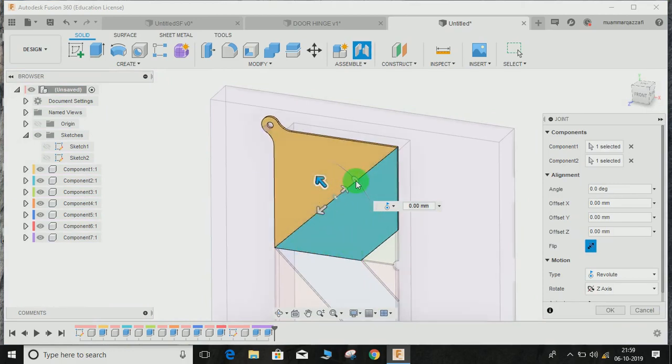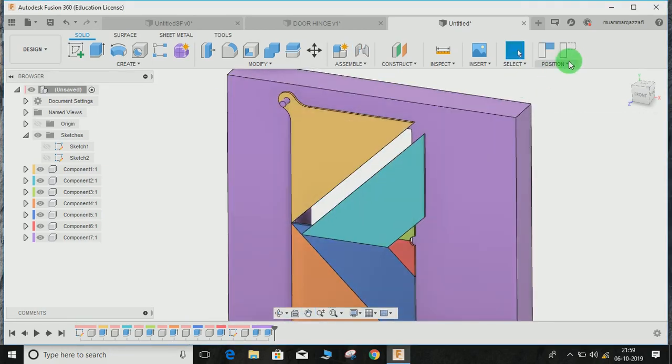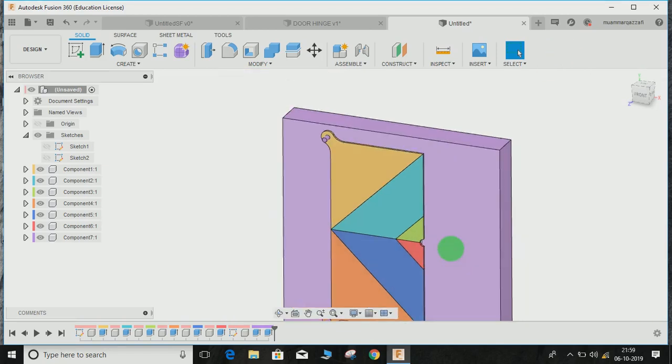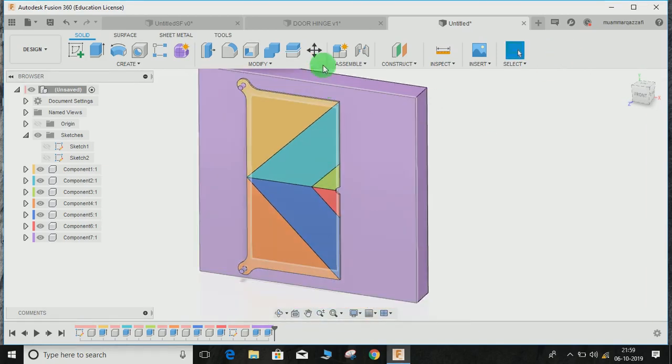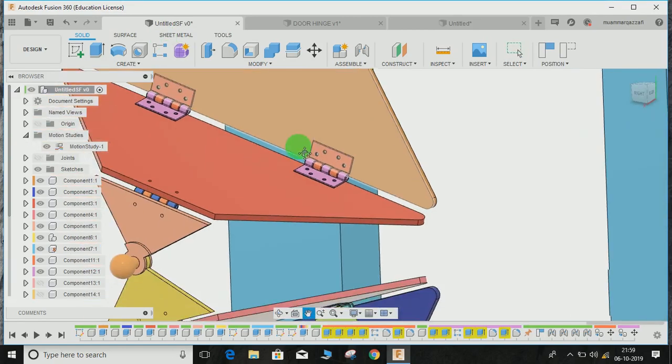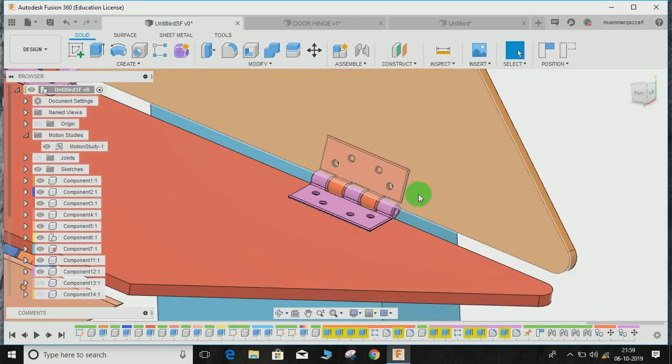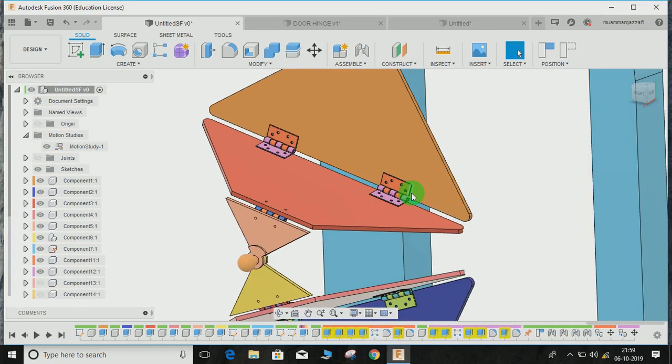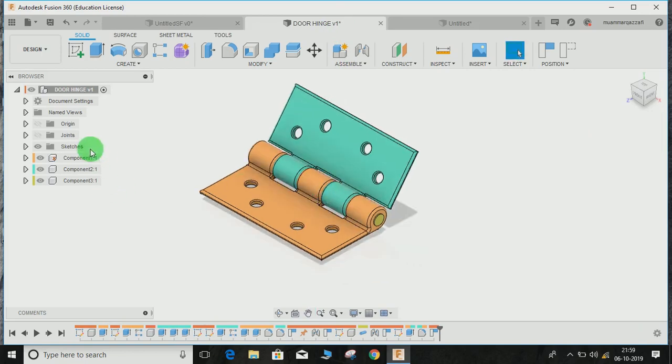But for the hinges, I need to drill some holes so that I can define the position where the hinges are going to be installed. So what I'm going to do is simply copy and paste from that design only. You can see the video of how to make these hinges. I haven't made any changes, and all you have to do is mark down the location of the holes and drill the same holes on these faces so that you can make the hinge on that part.